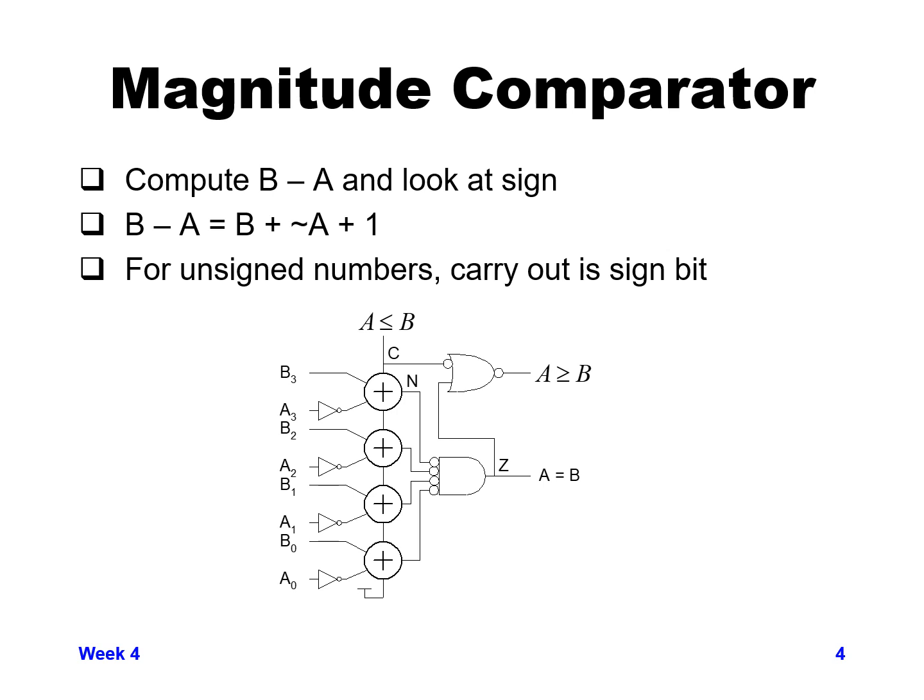And so we can take a normal adder and, for each bit of A, have an inverter that it goes through before it goes into the adder. And in order to do the plus 1, we just make sure that the carry in of bit 0 we tie to 1. And then we can get B plus not A plus 1. Then we just look at the carry bit coming out, and that will tell us whether B is greater than A or not.